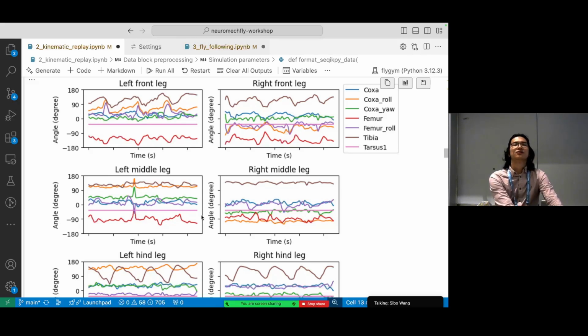It's a great question. So inverse kinematics by itself is just about knowing where the end effector is. Let's see what the kinematic chain must be doing. Imagine I have a robotic arm. I know that the end of the robotic arm has to be here because I want to reach for something. And then it's just a matter of calculating what the joints must be doing to make the end effector be there, right? This could be under-constrained. If your robotic arm is like a snake, then there are many different ways that you can reach that pose.